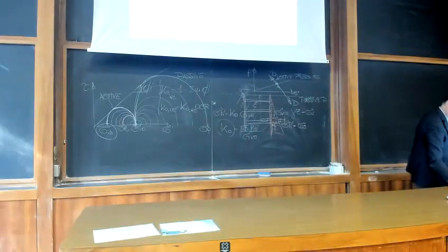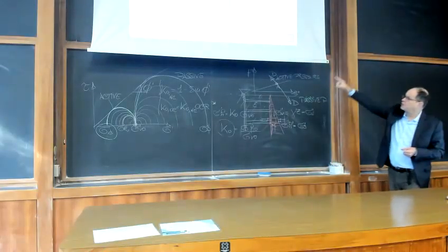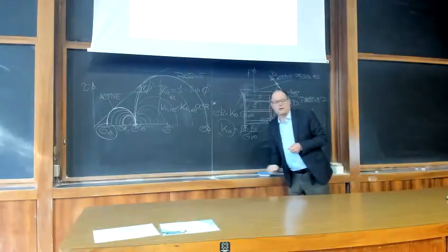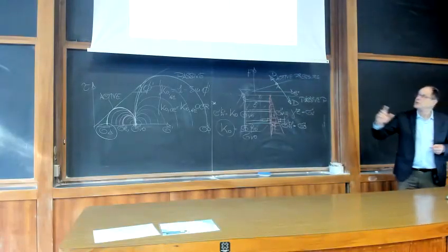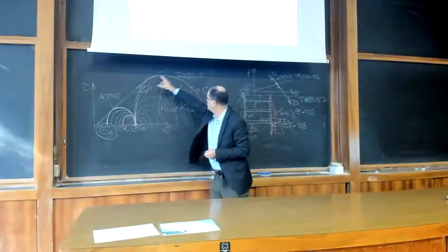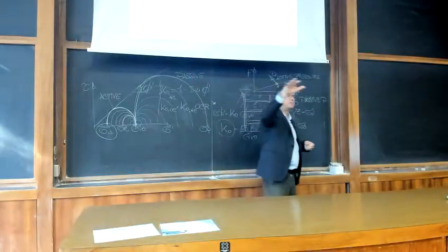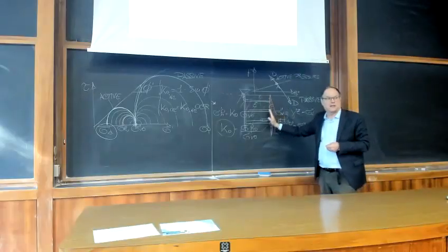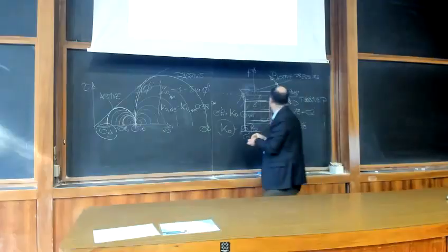Now we will derive this expression of the active pressure and of the active earth pressure coefficient in the following slide. But let's go to the other side. You see, in order to get into the passive zone, to get to this circle, you have to push against the soil. So this will never happen for a retaining wall. When can this happen? Just to remind you,